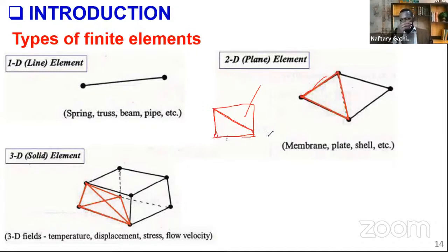I won't use this term, but maybe it might throw you off a little bit because of node degeneration. When you stretch or apply a load to a structure, of course, deformation occurs. Sometimes you may find a node stretches too much, such that you almost end up with 3 nodes where there were 4, because two come together. So that's one way we can end up having a 3-node plane element. Or you can just discretize.